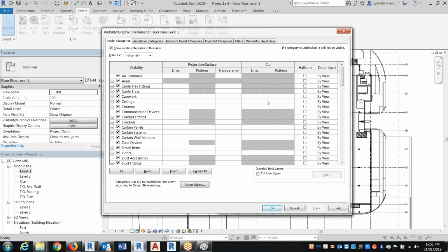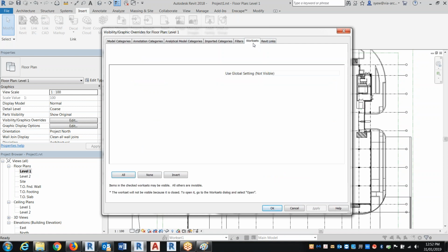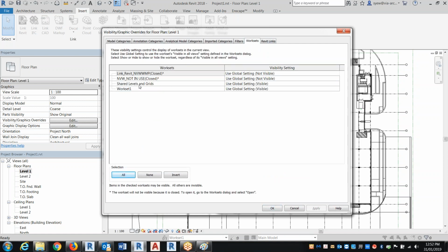For grids, if it's under structure, if they have a work set, then I would follow them, because they're the one who actually dictates where this column is going to move. Now, by default work sets, they usually have the shared levels and grids. I just say, okay, all my grids and stuff like that, just put it in there. If structural has their own way, I would follow theirs, same work set, so that you guys have the same thing.